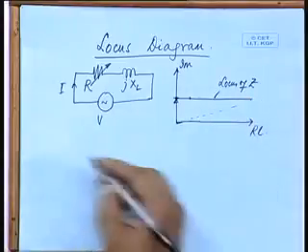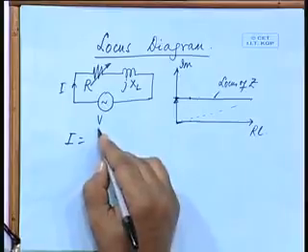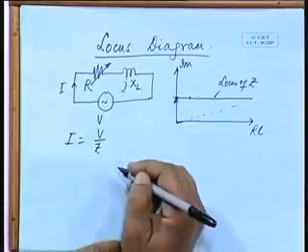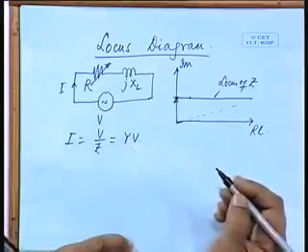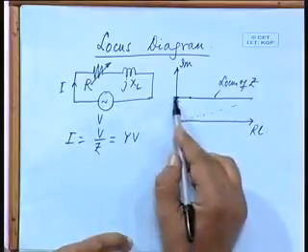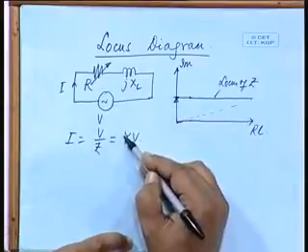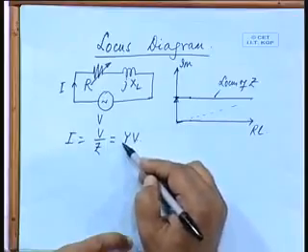All right. Now, what will be the current? Current is V by Z. For the time being, let us forget about the angle part at this moment. So, we can write Y into V, where Y is the admittance. Okay. So, if the locus of Z is known, what will be the locus of Y? Since V is fixed, the locus of Y will be a scaled version of the current I, is it not? So, how is Y changing with different values of R?